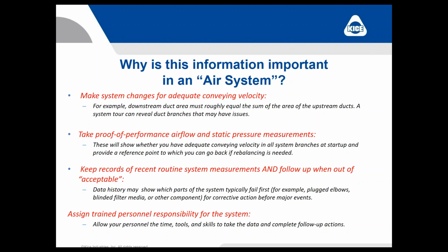Again, records are becoming more important every day, and so is knowing when to follow up when they get out of the acceptable range. So if you know this information, you can start to keep some history on it. And it's always nice if you have some assigned, trained personnel responsible for the system. Give them the tools, give them the time, give them the training to use an air measuring kit, and then they can help you when you decide to make follow-up actions.